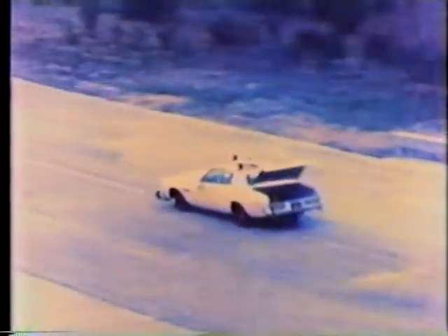This is a standard safety-shaped concrete barrier with an aluminum rail on top. The aluminum railing adds another 12 inches. Notice the shape of the barrier face, which sends the hood over the top of the railing and prevents snagging. This test is with the same kind of barrier. The test vehicle leaves the ground but is successfully redirected.